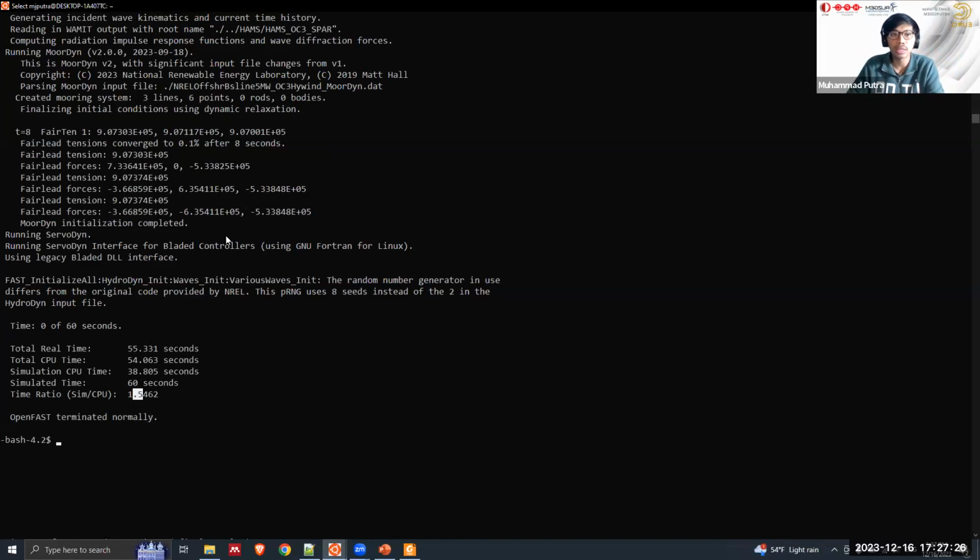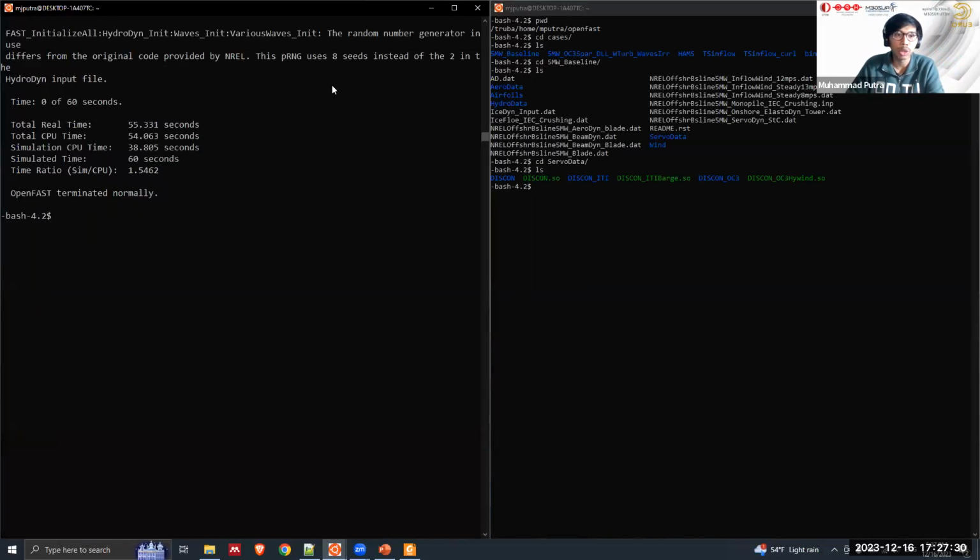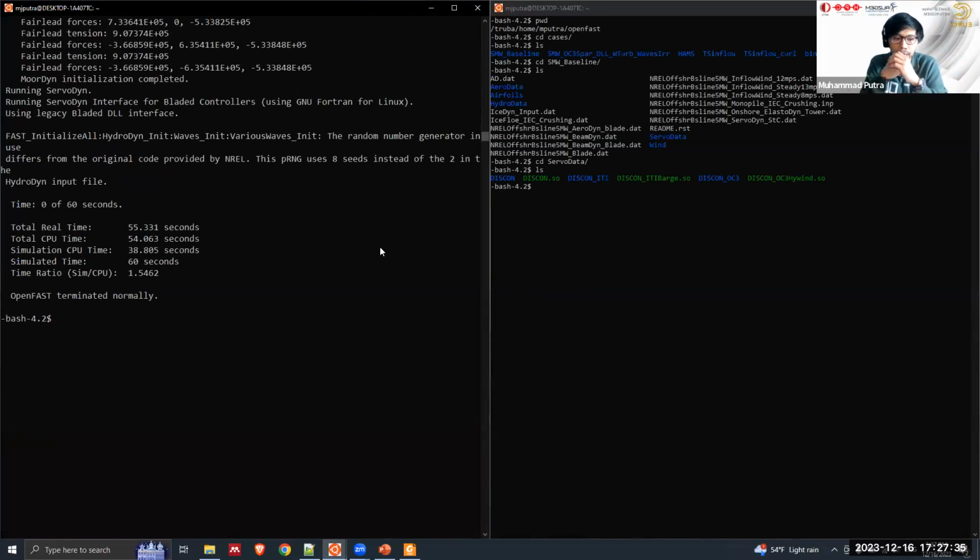This is why we need these mid fidelity simulations, because if you are working with high fidelity simulations like LES or DNS, like all my colleagues have performed earlier, they use OpenFOAM and SU2. If you run the full wind turbine there, it takes, I believe, days to weeks, but OpenFast is fast. The intention of developing OpenFast is not to eliminate those results, because those are high fidelity with the highest degrees of accuracy. OpenFast, on the other hand, should be called mid fidelity or engineering fidelity. So we can run more cases in OpenFast, pick several critical cases, and then bring those to high fidelity, so that we can use this to support the high fidelity simulators.